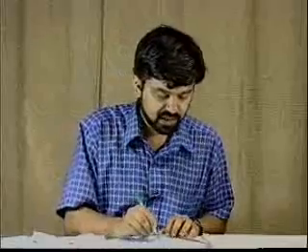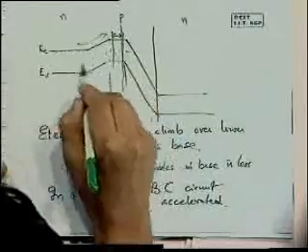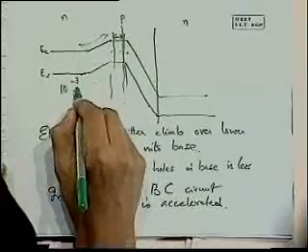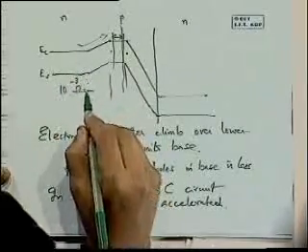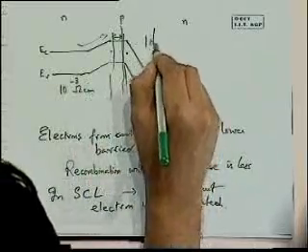From here, by using a very small change here, we can get a much larger change, because you're going to be accelerated there and have higher velocities. Now we can look at that a little bit more closely, how it is actually doing the amplification. When we think in terms of the resistance in this area, because the emitter base region, especially the emitter, is doped highly, we have resistance somewhere here of the order of 10 to the power minus 3 ohm centimeter, low resistance. Okay? And in this region here, we have a much higher resistance, say 10 ohm centimeter.